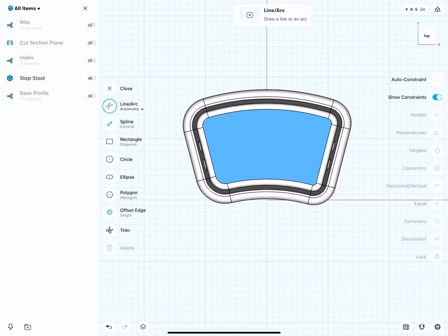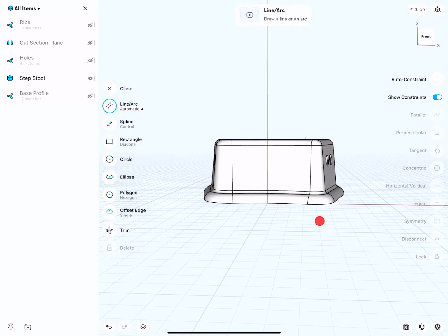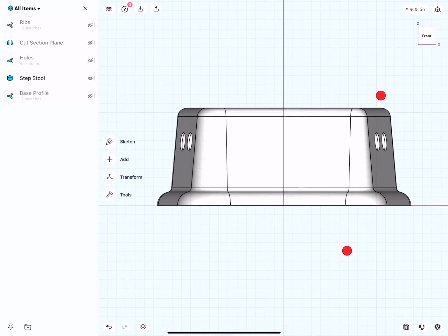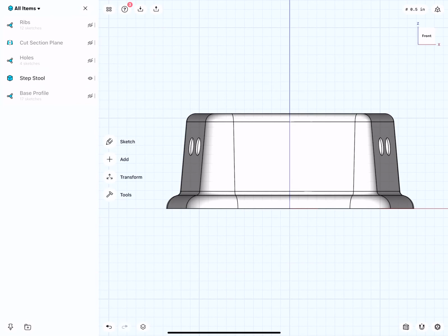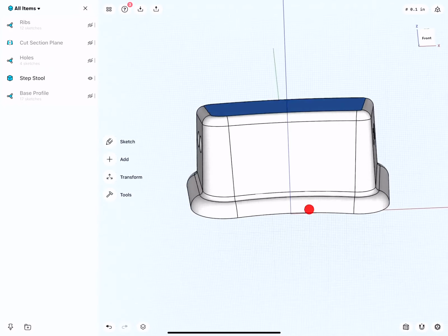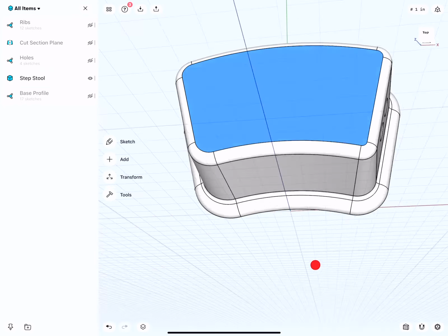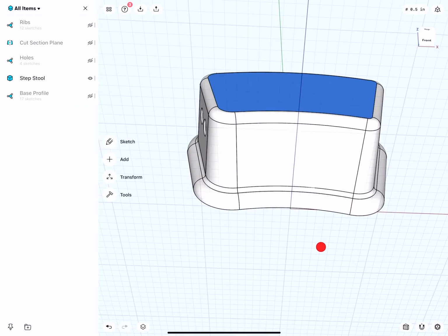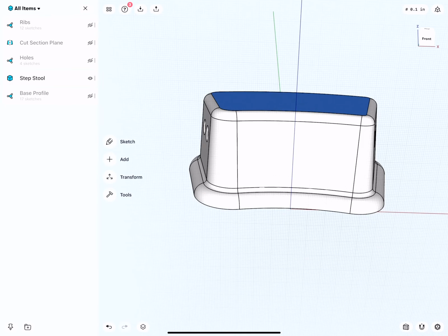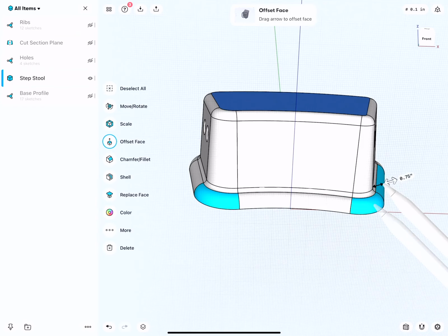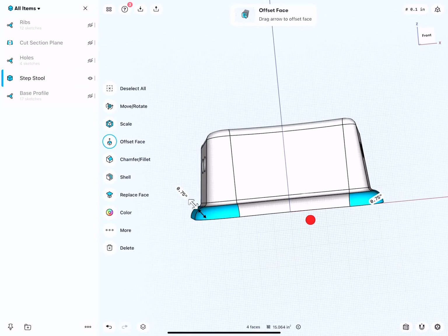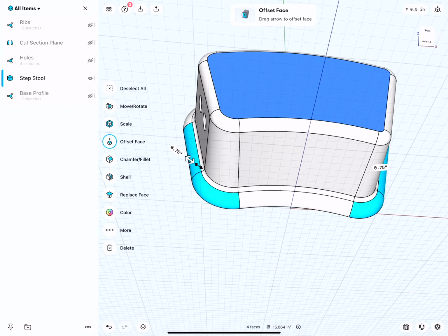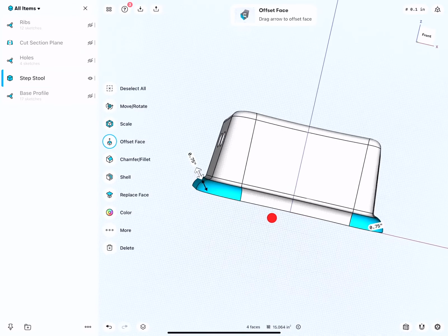It's a very simple extrusion command. We take a look from the front. What is interesting is that it's not just a straight extrusion that goes up. It is slightly tapered, and when we do the extrusion, we can simply use the built-in taper command. So we only need one sketch at the bottom to create this design. Also here, this is not created via a sweep. It's also simply an extrusion, but then I rounded it so it looks like a sweep surface.